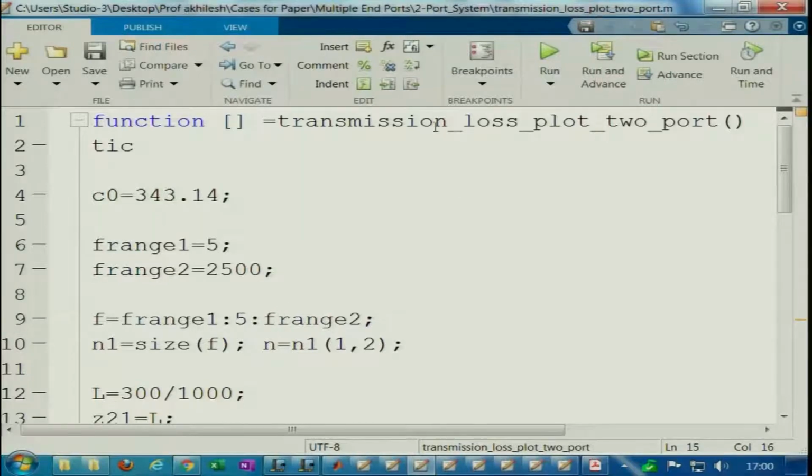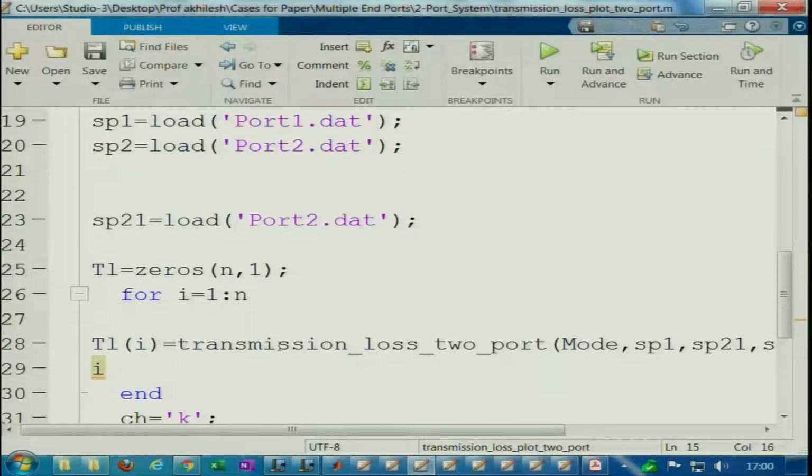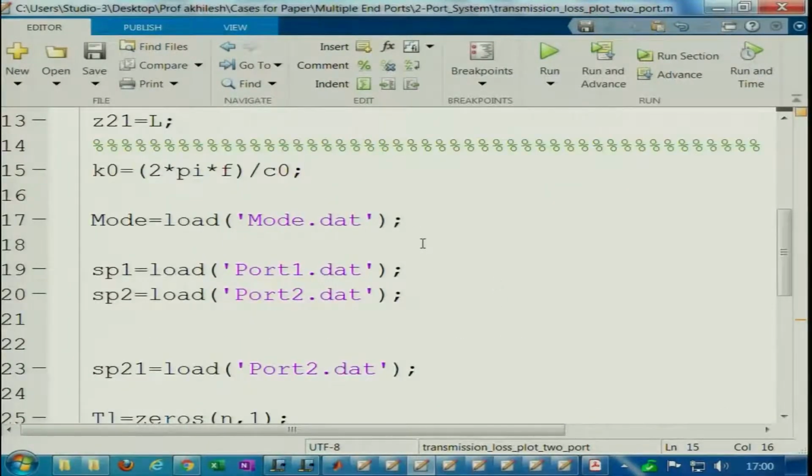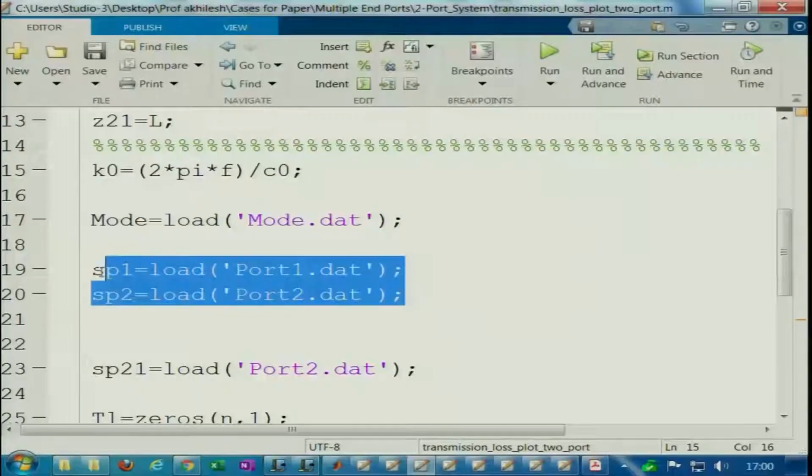So, as usual, we have the transmission loss port file, which is the main file, where the final computation of transmission loss from the overall impedance matrix is done in terms of scattering matrix parameters. So, a number of parameters have to be computed first: basically the n, L, m n value, the mode shapes, the integral of the square of the particular mode shapes of the chamber, and then the integrals for the particular port.